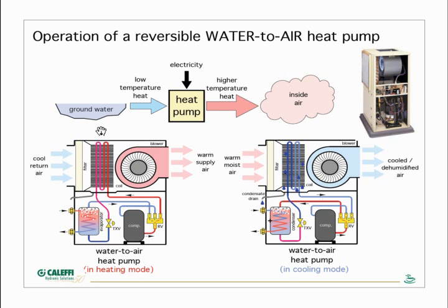And in the heating mode, that is warm air. In the cooling mode, that air is both cooled and also dehumidified. And you'll see some droplets of water over here on the coil, just like any AC unit would have. So we're getting both latent and sensible cooling.